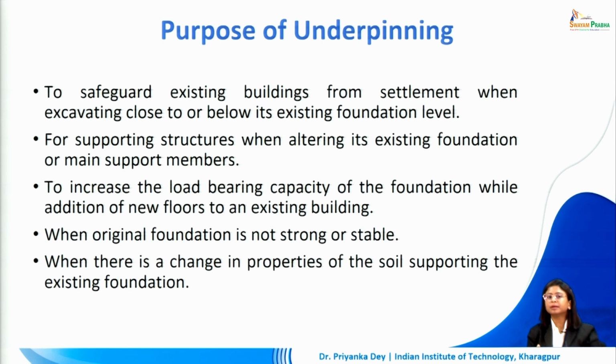let's say we are doing some construction work where we will be required to dig up very close to an existing foundation level, or we are creating a trench which is deeper than the foundation level that is already existing, it can cause damage to our building. So in order to protect our building, we can use underpinning in that situation when we are doing excavation very close to it. For supporting structures, when we are altering its existing foundation or some main support members have to be added or changed, we might need to go for this process as well.